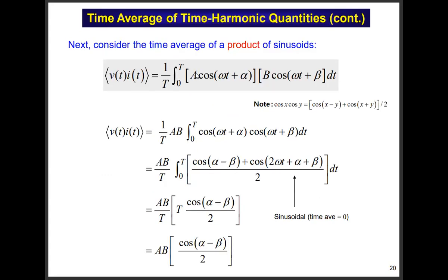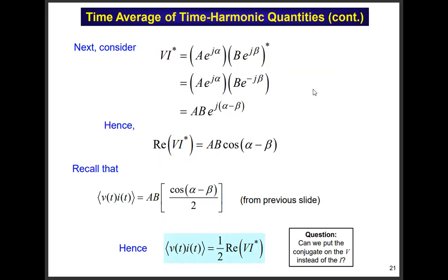All right, so time domain, remember magnitude phase, right? Magnitude phase. So here's voltage phasor A, voltage phasor B. You know what the conjugate does. Phase angle gets replaced by its negative. So we get like this. And then something interesting and useful happens if we take the real part of VI conjugate. Remember Euler's identity, so that's cosine.